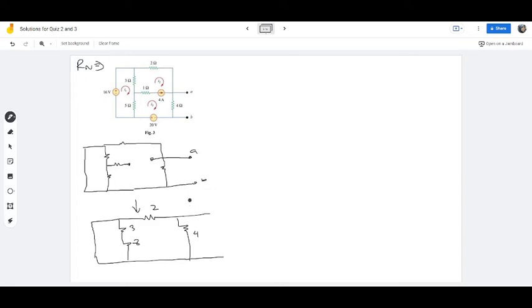Alright, so now what do you notice? You notice that there's a short circuit again, madam. You and your short circuit. That's correct, this is a short circuit. So just like that, this 3 and 5, this is supposed to be 5, it's not 8, this is 5. The 3 and 5 can be ignored because the resistor is short circuit. They are both short circuit.